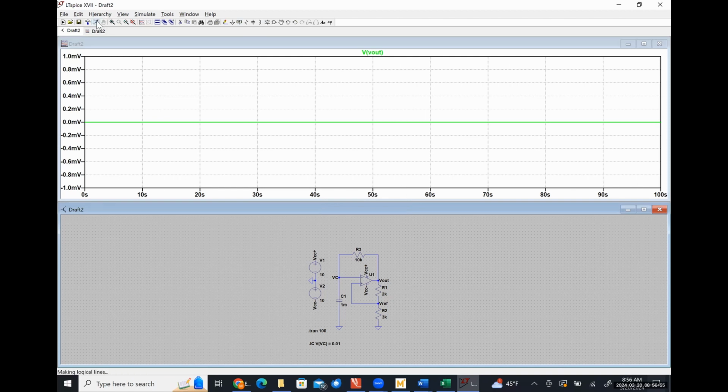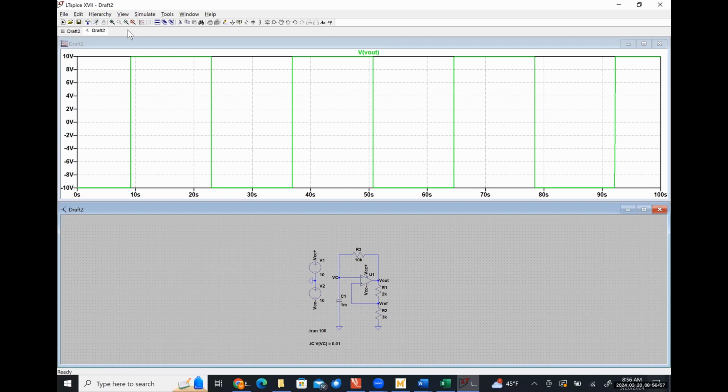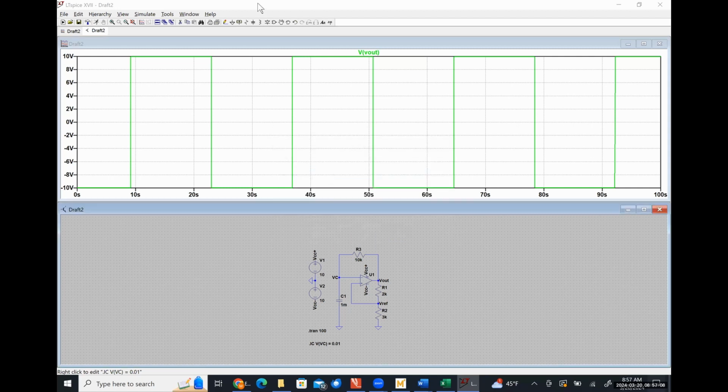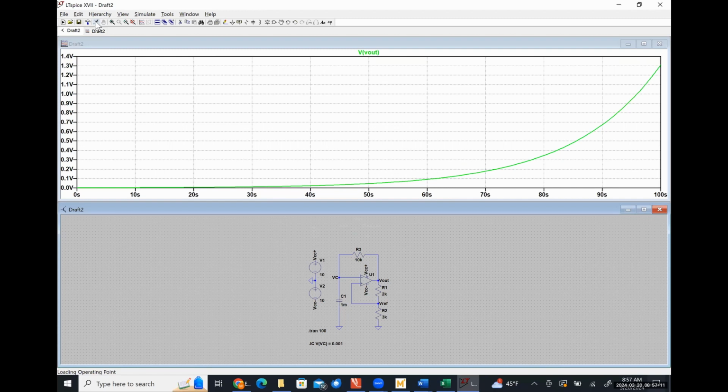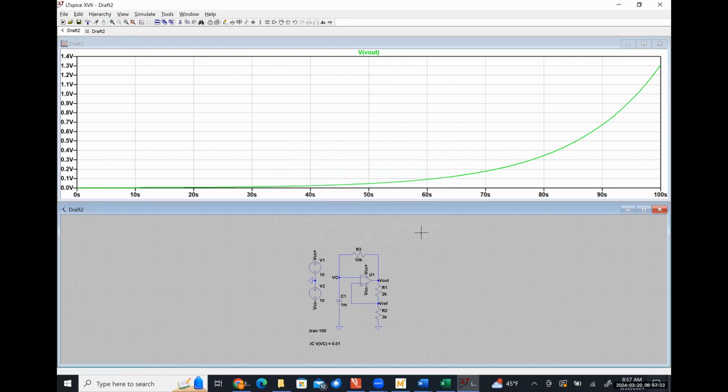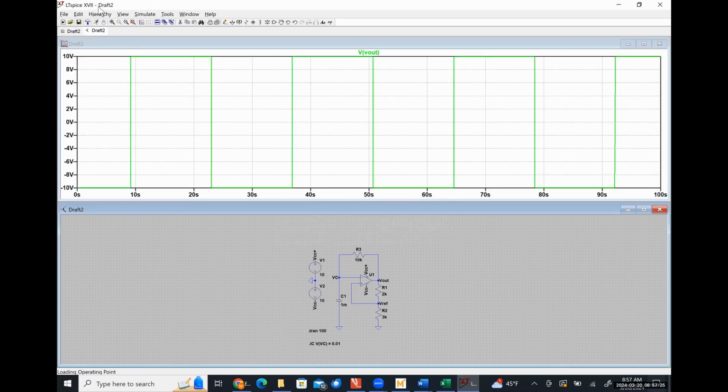So if I rerun this simulation, now I can see that very quickly everything starts kicking off. Just for the sake of argument, let's make this initial amount of voltage on the capacitor a millivolt. We can see it takes some time to start swinging up, but it'll do it. So it really doesn't take much energy at all for this to happen, which is why we don't actually need an input signal. In a real electrical network, there's always thermal energy in our system because electrons move around. So that's literally enough to kickstart this thing.